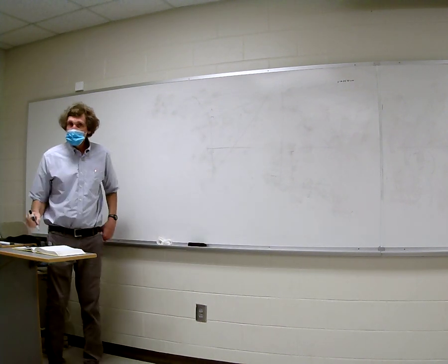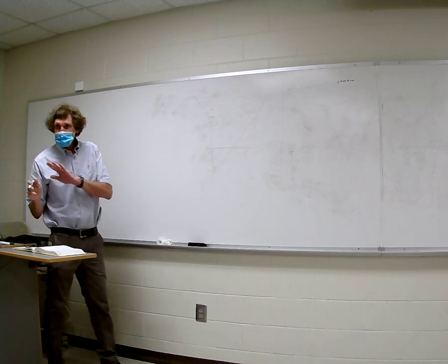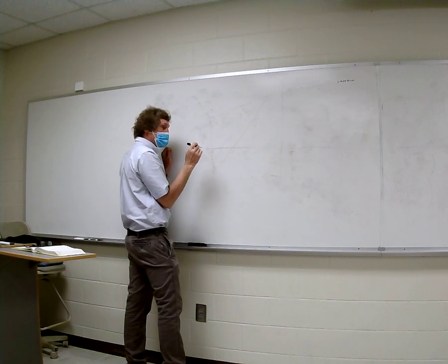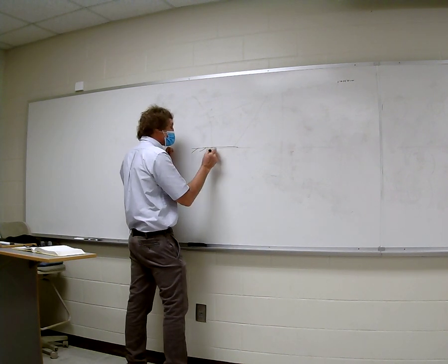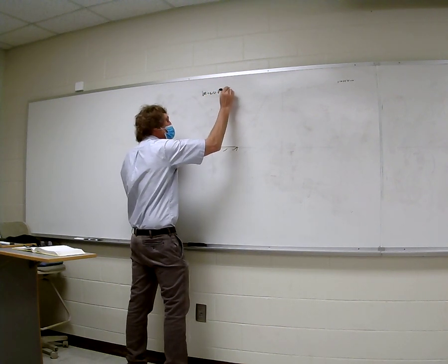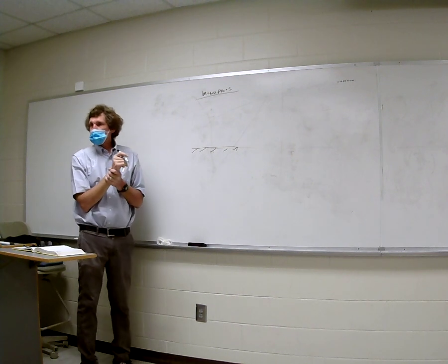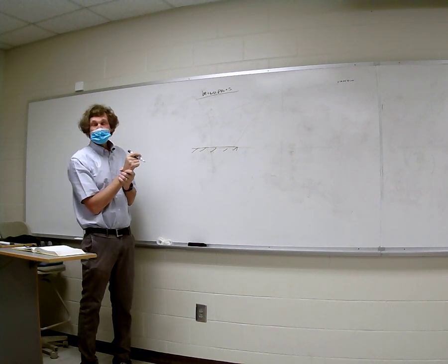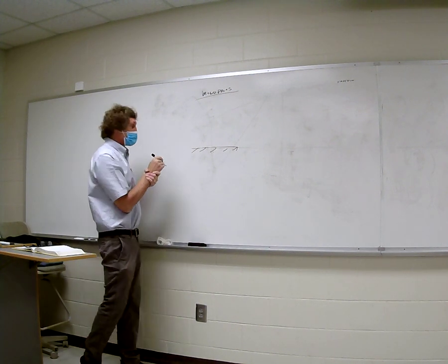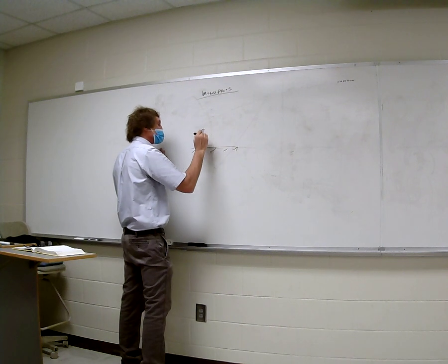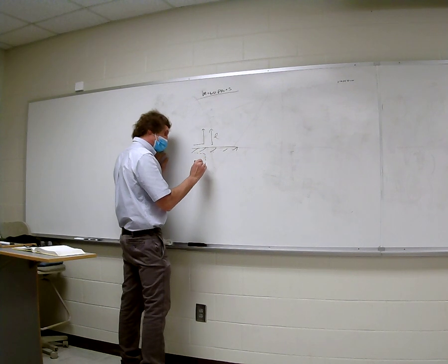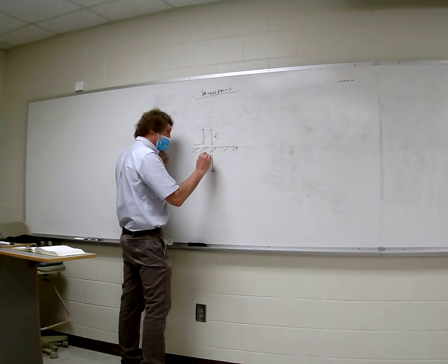All right, finally, I'm trying to wrap up everything before I get into the array factor. Finally, when we talk about real-world antennas, what's the effect? They're called monopoles. And if you watch the lecture, I talked about monopoles. So what's a monopole? It's half the length of the dipole you're talking about. That's all it is. So if we talk about a short dipole, if this is going to be length L, well, really, there's an image down here of length L as well.